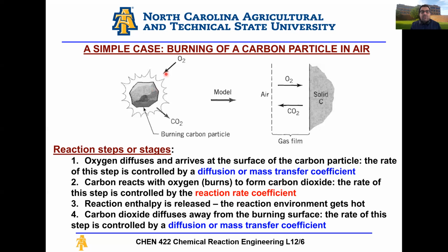And in multi-phase processes, this is actually quite common, where the design of the reactor now is a function of the mixing pattern, right? The mixing pattern starts playing a more important role than the catalyst or the nature of the reaction, because I need to find the best mixing profile that's going to minimize my mass transfer resistance so that my overall reaction can proceed faster.